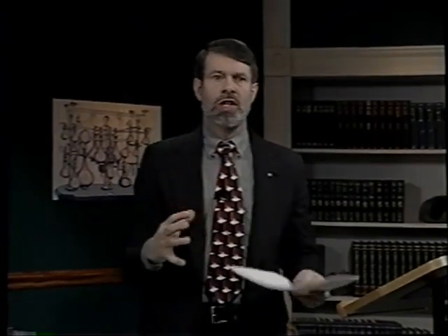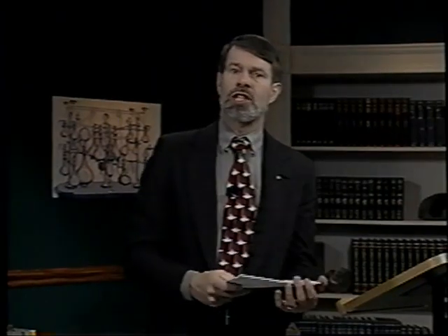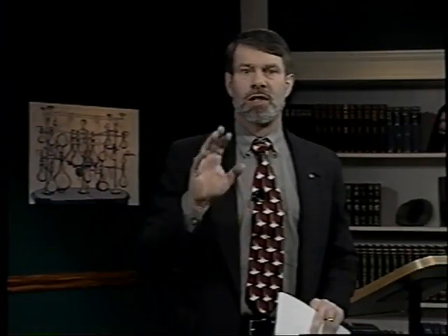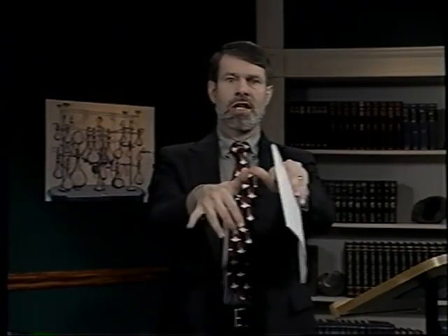And then we had shear strength, the twisting of a material. And only if you had a rigid cross-linking in 3 dimensions of bonds could you have a material that was strong under twisting or shear. I also talked about thermal expansion, the fact that many materials expand when they're heated because the atoms, as they move faster and faster, bump into each other. But a few materials with very, very strong bonds actually contract when they're heated because strong bonds link together, and as the angles get larger and larger, the atoms get closer together.